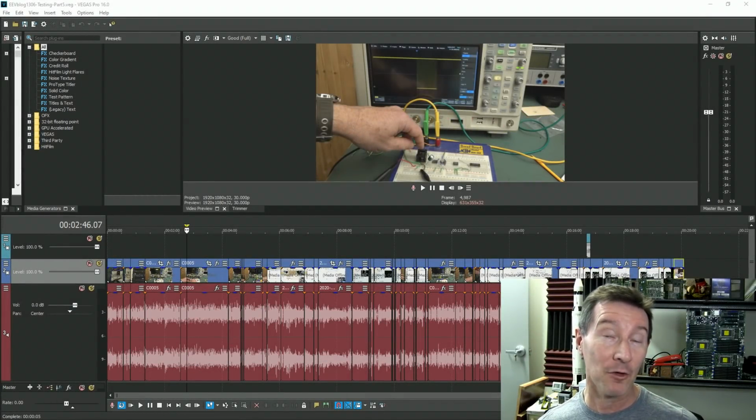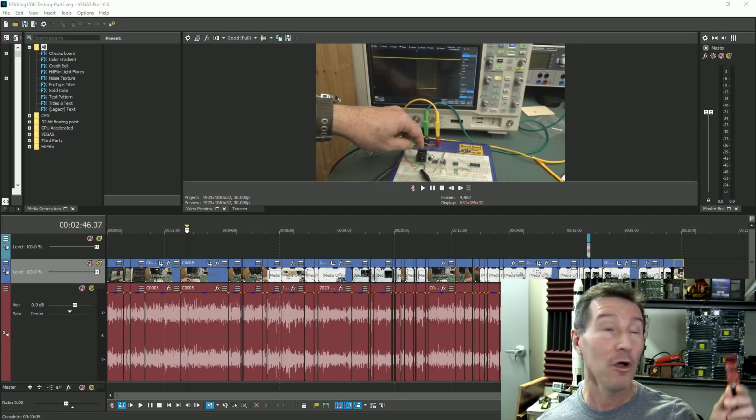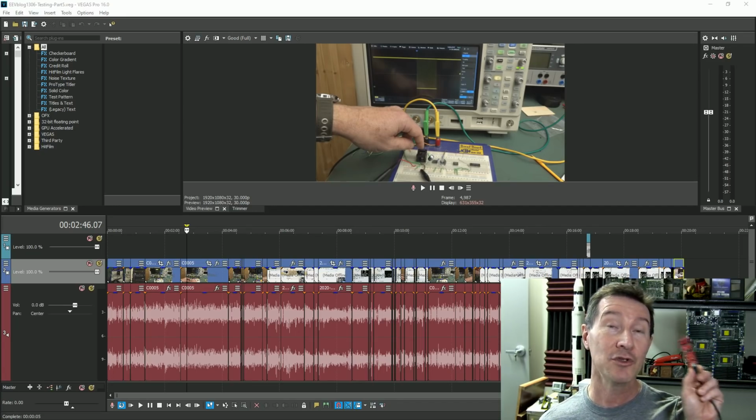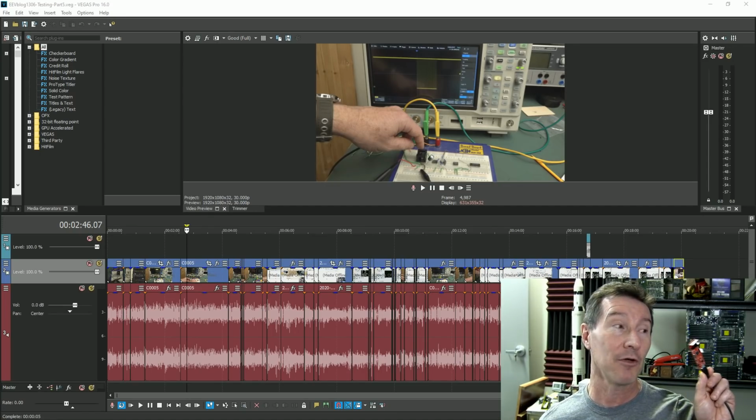Hi, welcome to the final part of our Padauk 3-cent microcontroller programming series, where we build up some open source hardware and software to program these 3-cent microcontrollers. Now, in part 4, we took a look at actually using the SDCC compiler, the Small Device C Compiler, to program a file and generate an Intel hex file, which we can use on our programmer to program our little chip. So we're basically just taking an existing pre-written example file and compiling it, generating the Intel hex file, and then simply running the command line programmer to program that Intel hex file into our chip.